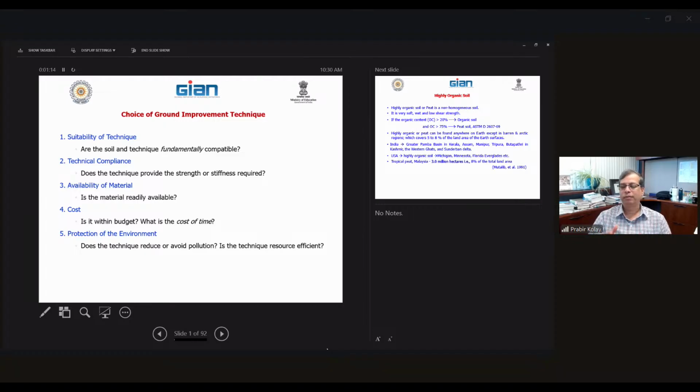The conventional admixtures, cement and lime, and industrial waste, fly ash, GGBS, and others. And then the non-conventional, you can use polymer, you can use different geopolymers we mentioned, and then durability of that. And then the last part is inclusion, something you include into the soil. And the soil nail is also an inclusion, right? So the soil nail is also part of this last portion. Basically, you need to reinforce the soil, either MSE. And so first we'll talk about highly organic soil, how to stabilize the organic soil, and then we'll talk about the retaining wall design.